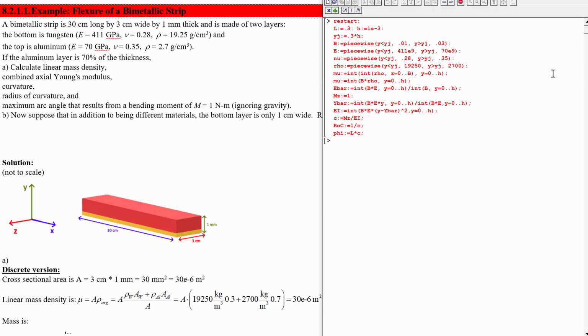Right, okay. So this gives us, how does the angle compare to before? If we make the tungsten less thick, then we should be getting more angle than we had last time, where it was 0.85. Yep. So the same moment is going to give us a lot more bending because we have less resistance, a lot lower flexural rigidity than we had earlier.